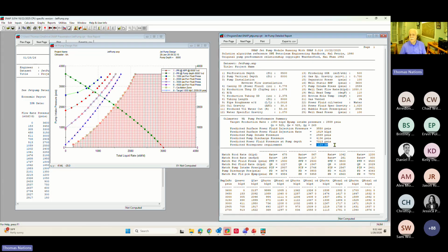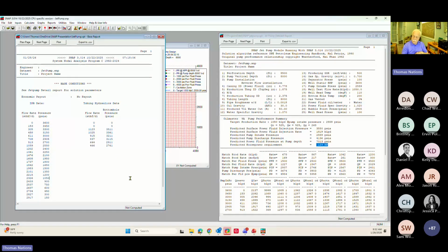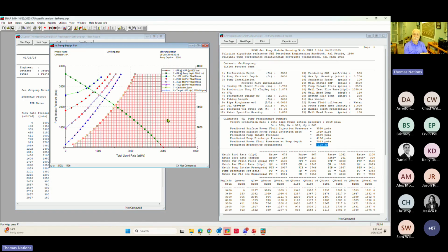So doing this is kind of iterative, I guess. You just put all your PVT information, your IPR information, all that has to go in here, because everything is based on this IPR, right? We have to honor that, and what our well is going to produce is going to be where our pump curve intersects our IPR curve. Same thing for any nodal analysis plot. It's the intersection where all of our stuff agrees. All right, so that's pretty simple.